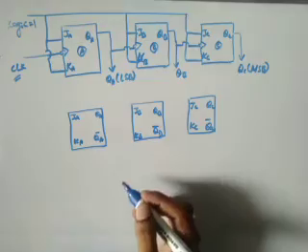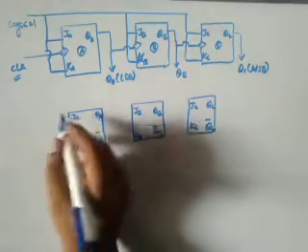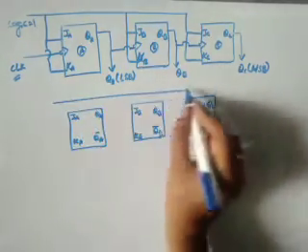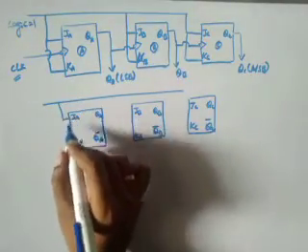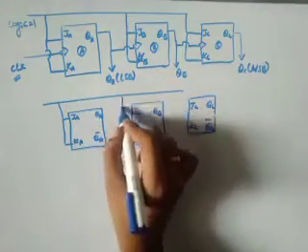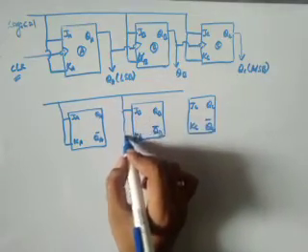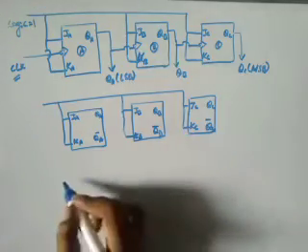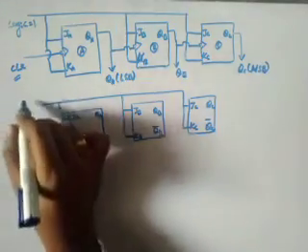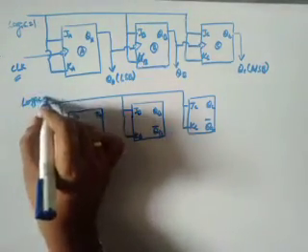Since definitely it has to be in toggle state, we have to give the value of J and the value of K as 1 always. That input will not change. We should not give any other values. So this logic is always 1.